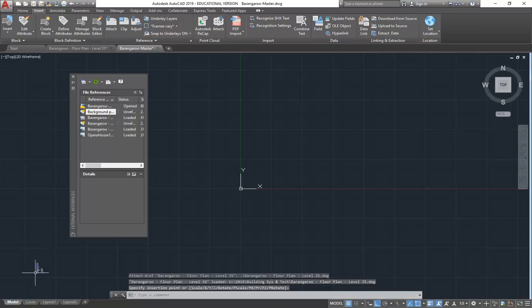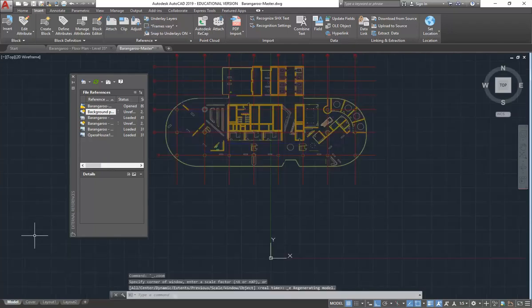So there we are. So I've placed it, and now to see it, I'm going to double click with the wheel, and that's going to zoom out, and then I can see everything. Double click with the wheel? Yeah, that does zoom extents.